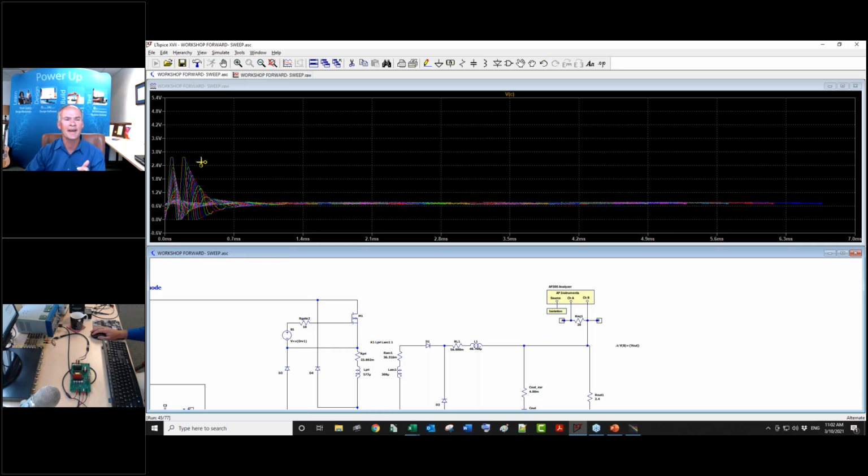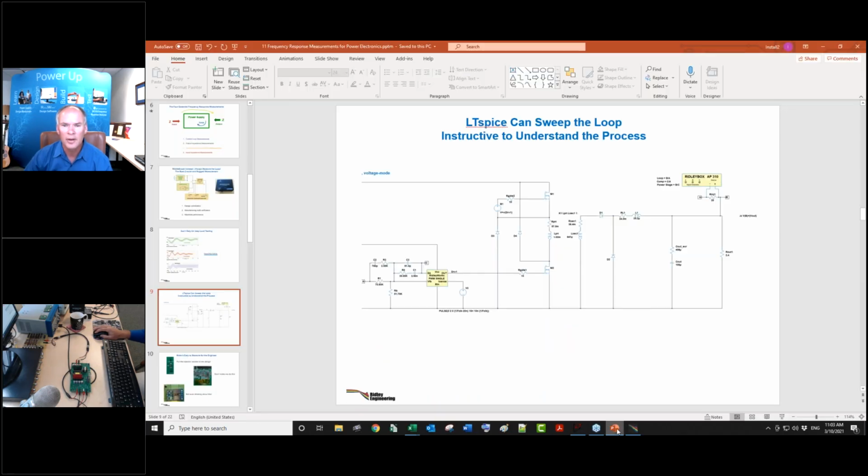And you can see that now it's overdriving on the top, and it's clamping to the peak voltage of the error amplifier. So if I tried to plot this loop gain with that constant 0.6 volts, I would get terrible results as it approaches the crossover here, because I'm just saturating the amplifiers and everything's nonlinear at this point. So you can't use these results. We'll leave that running, and we'll come back to that if it makes sense.